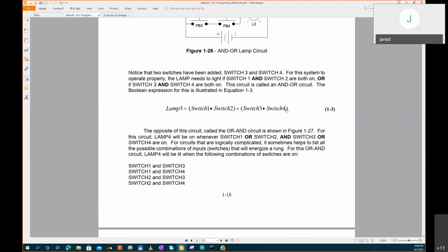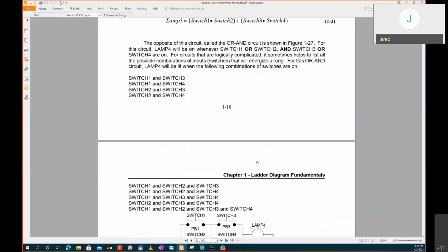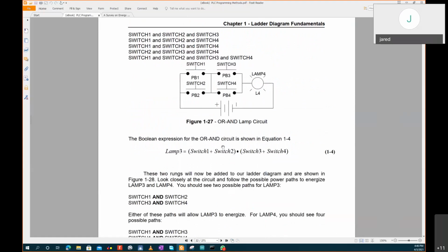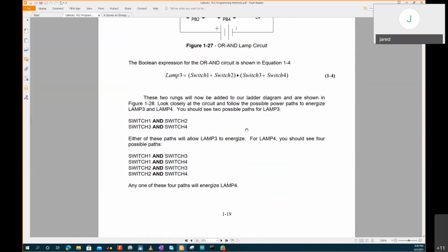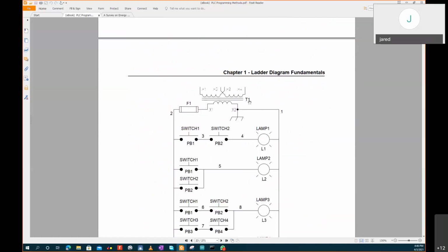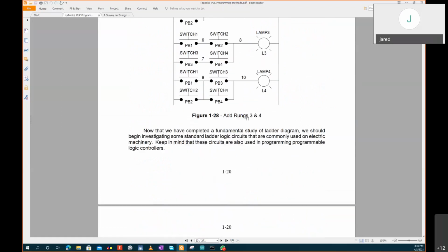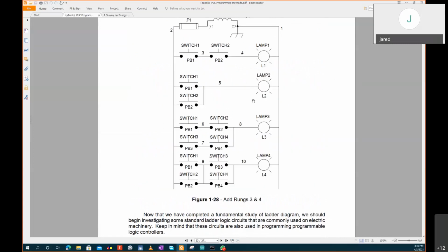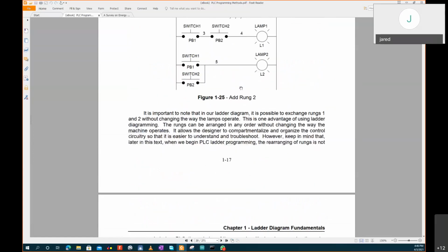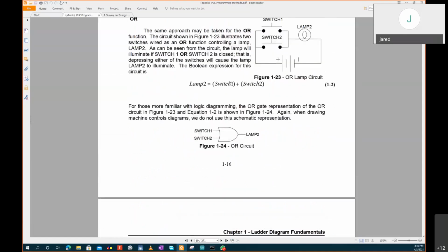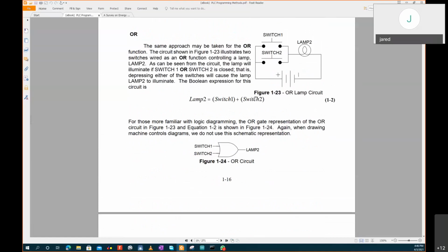So this is the statement, and then you come here and write your lines, and from there you represent it electrically. Then from the electrical representation, you go to the ladder PLC logic representation. And this is a rung of our logic. I think that's quite much of what we did yesterday. This is the OR gate, how it looks. And this is the logic statement. This is the symbolic representation in a digital format.